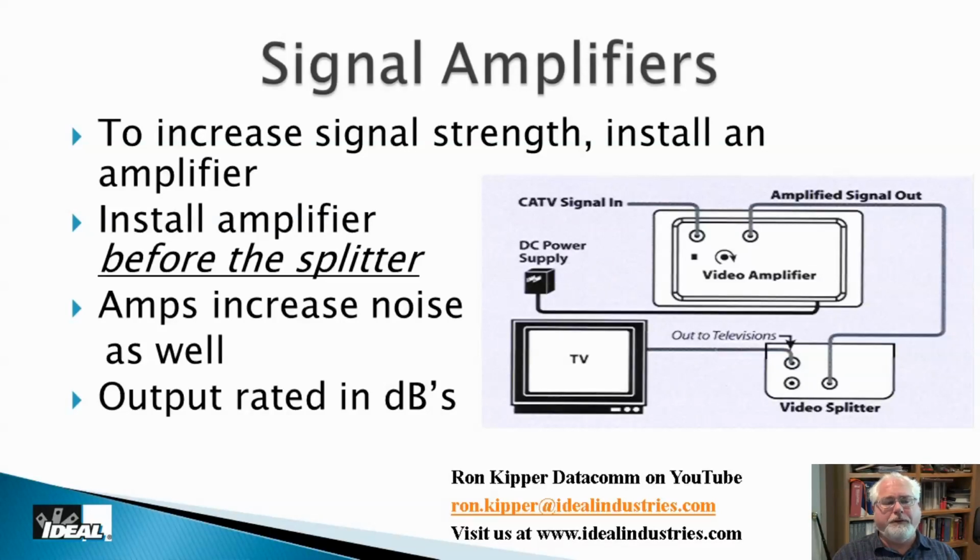And in a lot of cases, those old amplifiers were not ready for a high enough frequency. They're not ready for digital high-def stuff. And they don't have much, if any, of a return path in them. Today, there are things like modems out there, and those modems need to talk to the outside world. Your set-top box needs to talk to the outside world, and it can't do that if there's not a return path in the cable. So signals are passing both ways through the cable. We call it bidirectional. So that's another term you're looking for on an amplifier.